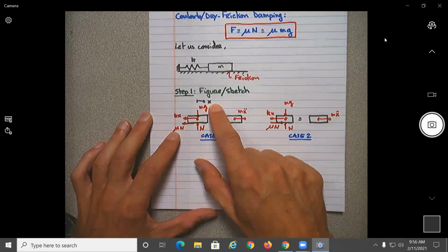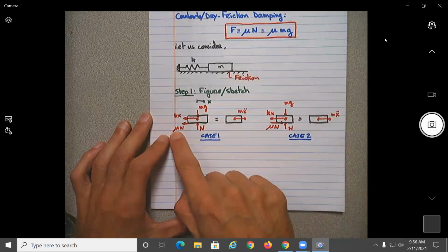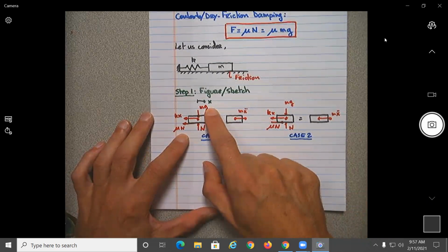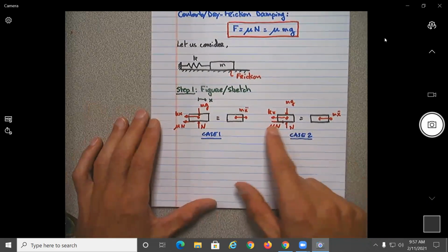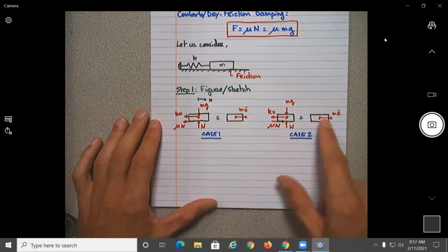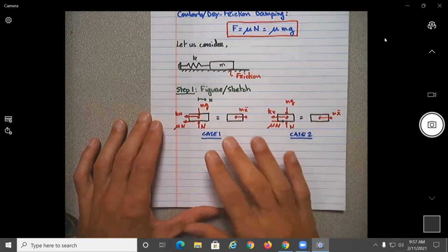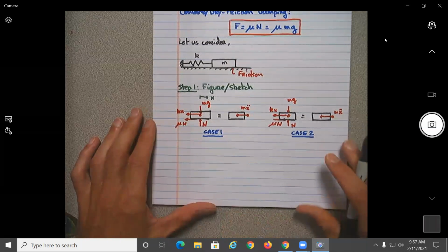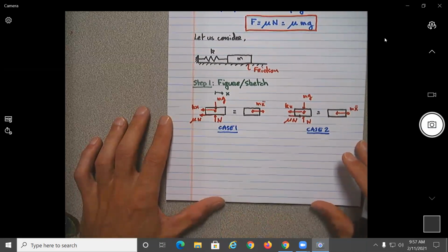No, the friction force is just going to be a function of mu, the dry friction coefficient, or the kinematic friction coefficient, times N, and N is equal to mg. So that's absolutely not related at all to the current system. Agree? That's why I'm just specifying that this would be the different one, and the rest I leave like in the general current system. So that's really the two cases we can have when the object is moving.